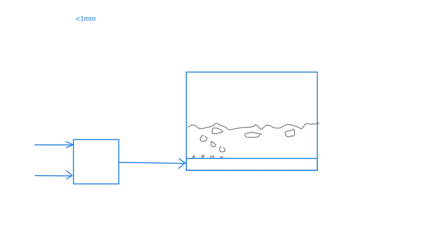So bubbles tend to grow. They'll start small as they come out of these little holes in the plenum, and they tend to merge together in a fluidized bed. So you can't make a fluidized bed very deep. Probably the deepest you will go is about 1 meter, but 300 millimeters is more likely.